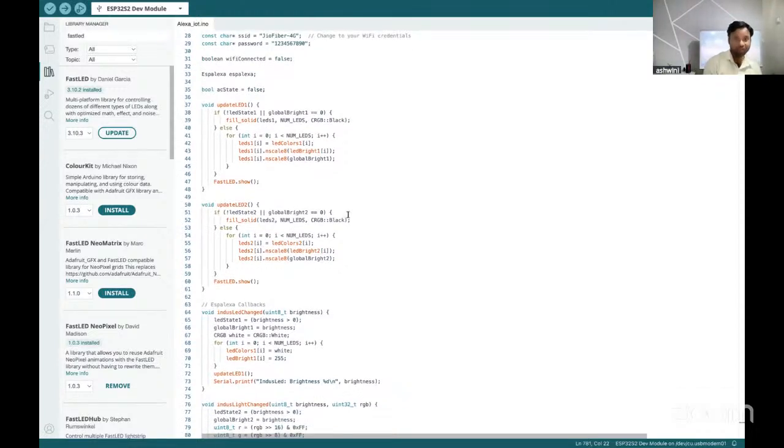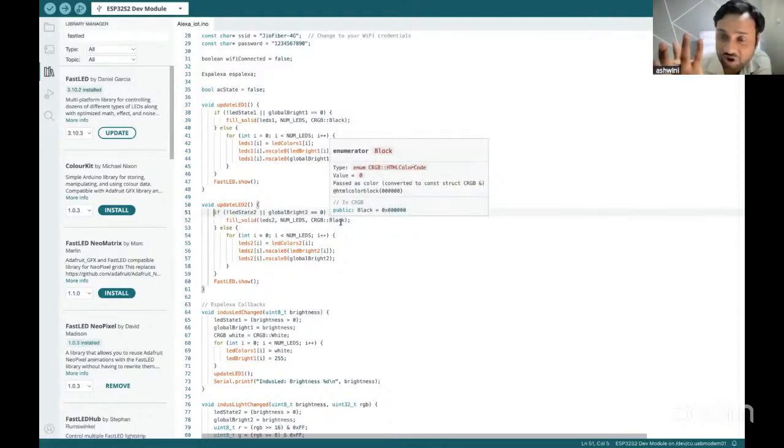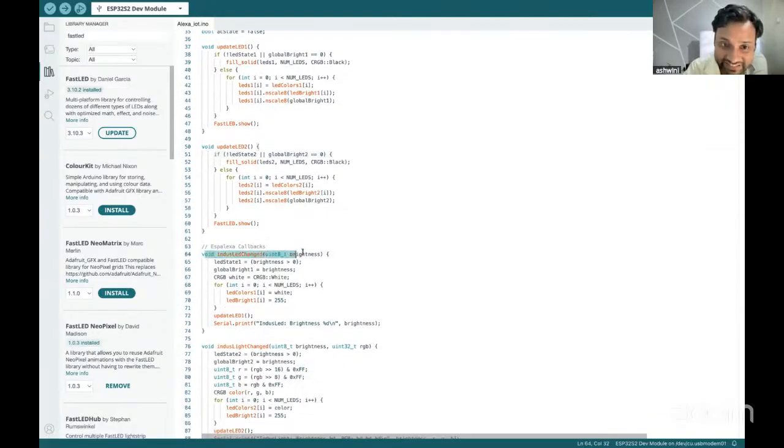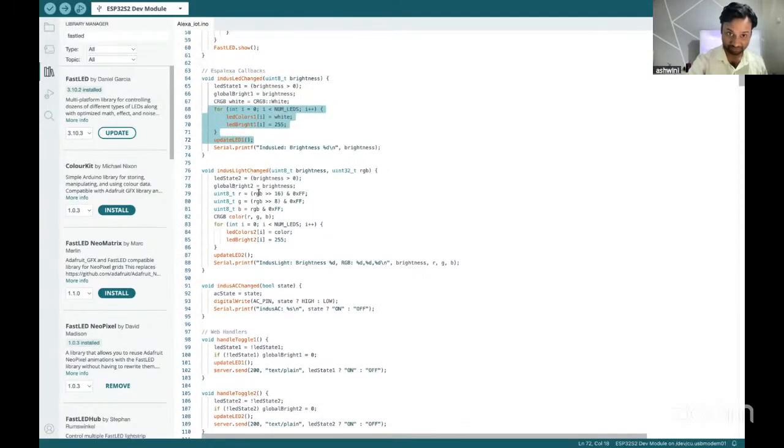Now in this part of the code, you need to check the LED status command that will be sent to Alexa, and Alexa will return the command saying the status of the LED, whether it's saying to turn on or turn off, the brightness, or the colors. You have to check the status from the Alexa server, and once Alexa returns that, you have to set the same state for the LED or relay, whatever you have connected. You have to make an individual function for all these.